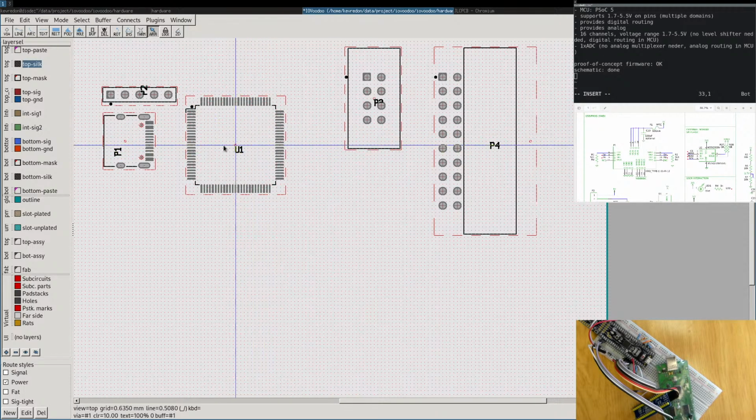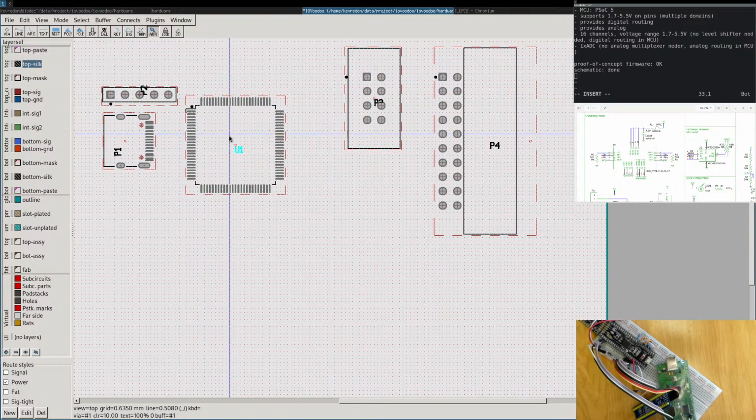And yep, the reference designator here, you generally want it outside because afterwards you want to read which component. It is mostly important when you populate the device, so you know which device goes where. But once you populated it, for example, if you have this chip on here, you wouldn't be able to see U1. So for debugging, it's not really useful.